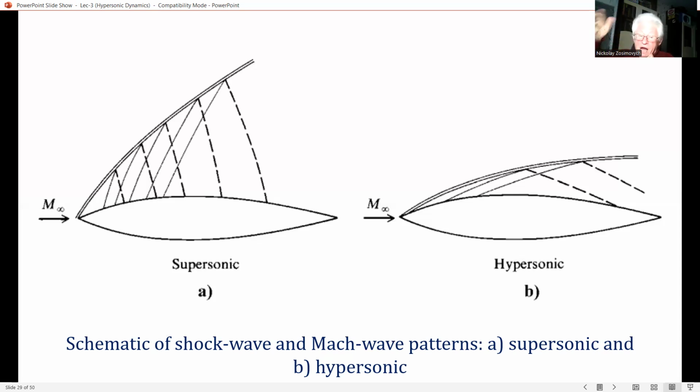Okay? Where our Mach number is the local Mach number. At low Mach number, mu is very large. As a result, as you see in this left figure, the reflected wave influences a considerable portion of the body surface. And this influence is not taken into account by the shock expansion method.